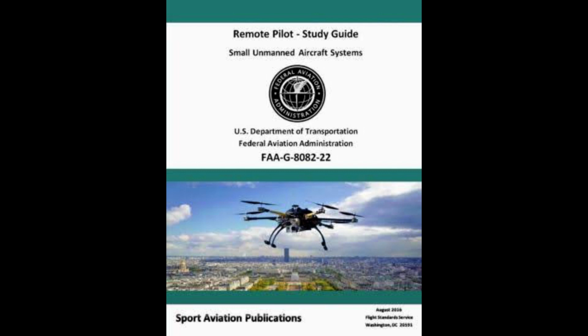The remote PIC should determine how the CG will shift and the resultant effects on the aircraft. If the CG is not within the allowable limits after loading, or does not remain within the allowable limits for safe flight, it will be necessary to relocate or shed some weight before flight is attempted.